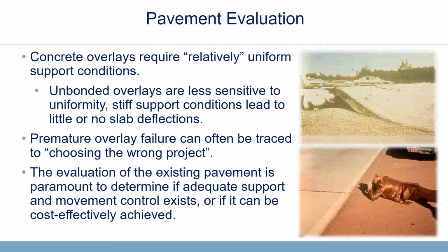Pavement evaluation probably doesn't have to be anywhere near as serious as these guys had gotten, but it is important. Concrete overlays require relatively uniform support conditions. Unbonded overlays are less sensitive to uniformity, and stiff support conditions lead to little or no slab deflections.